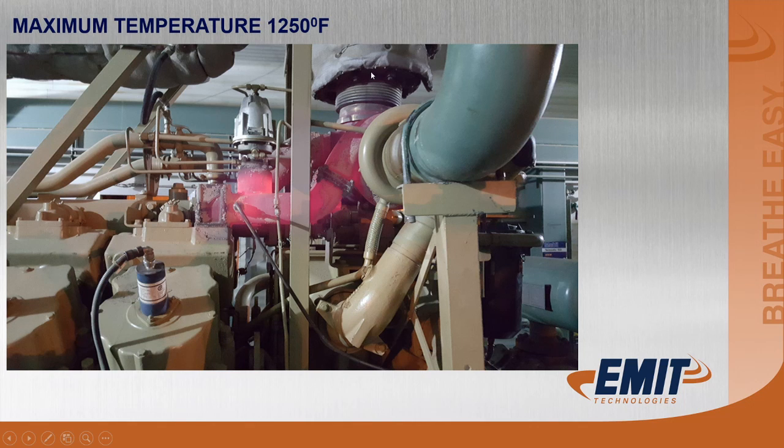On this particular unit, the insulated pipe had joints in it and had leaks under the joints. We were seeing catalyst temperatures right at 1250 on the inlet of the catalyst and about 1300 out. And their only issue was the engine was continuing to richen up as they tried to make it meet emissions because of the exhaust leaks in the joints that were underneath this insulation. When we tore the insulation off, we could see the leaks in the pipe. It's not uncommon though for a Waukesha to run this hot.